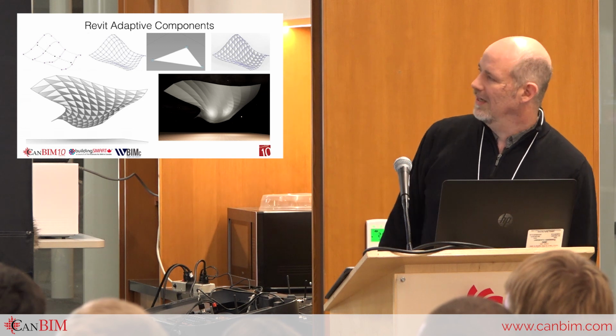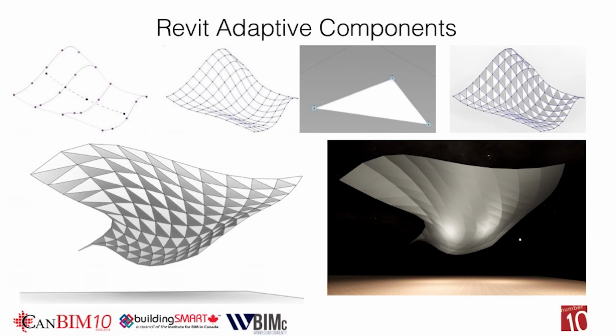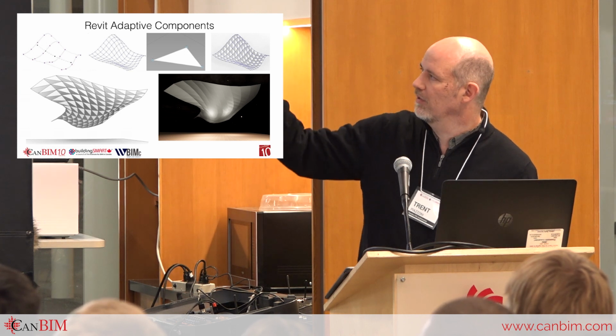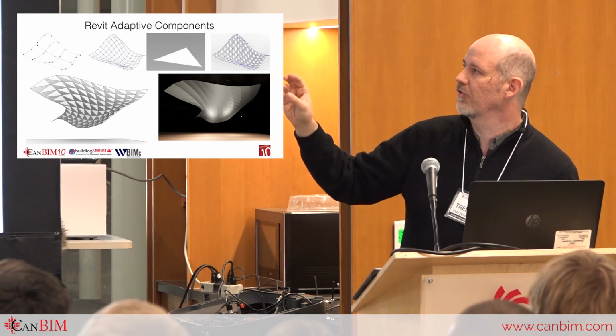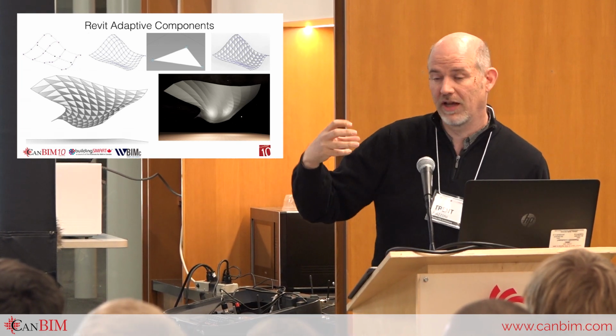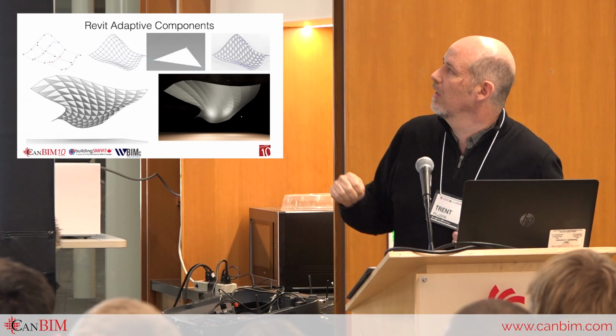And then you could insert a family, and in this case, it's a triangle shape. This is really what an adaptive component is, and adaptive points. So this triangle can be manipulated and stretched as needed. Each of those from point to point is a length, and the angle between those two has an angle associated with that. So that's all information that we could use for fabrication. After placing a triangle, you can all of a sudden fill those gaps and create that shape. Use the triangle because it's easier to create bendable tools. You get less distortion in it.